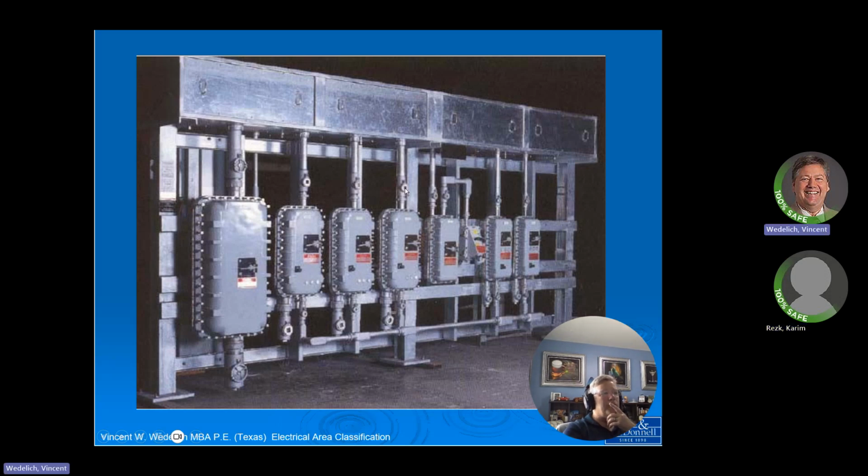Called conduit seals. Okay, got it. Yes. And what they do is, up here in this bus, it's open. Air can get in there, breathes and stuff like that. This guy breathes as well because there's a breather drain device on the bottom of it. There's low point breather and drains on these conduits as well. But this particular seal is filled up.